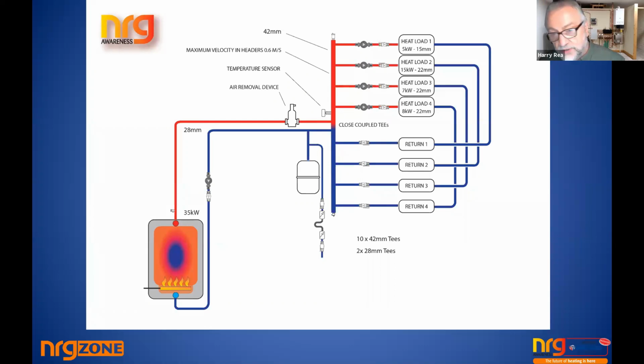So what I'm going to do in a lot of situations with this is show one boiler, but in reality, the images will be showing 2 boilers, but really you can take 1 or 2, it doesn't matter. If you're annoyed with the second boiler, close one eye, it doesn't matter. So what I'm saying is the amount of heat, no matter where it comes from, goes through the pipework. So for a 35 kilowatt system, you should have 1.5 inches.